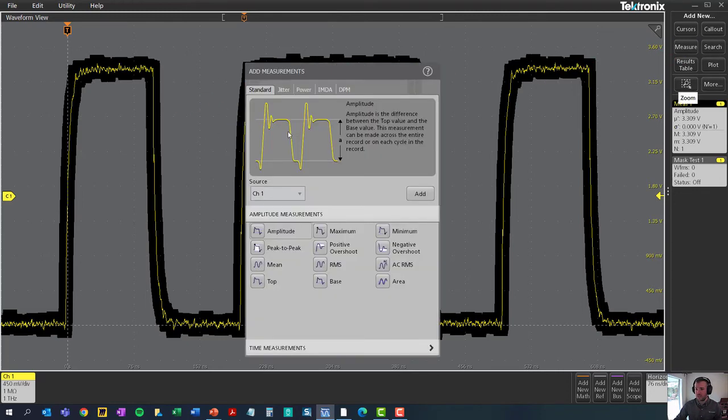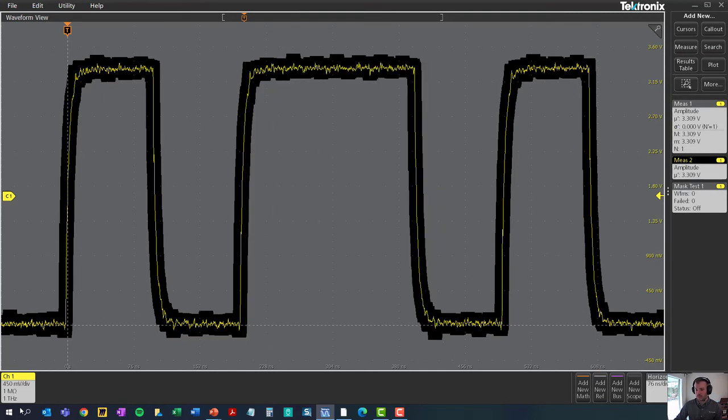Everything that we were doing, right? Drag and drop, add a measurement. I can turn channels off. I would be able to pull in references, and using this Tekscope, I can pull together dozens of signals. So you're no longer limited to 8 inputs, but many more, 16, 32, and you can do more complicated analysis. You just need to think about how you trigger those multiple instruments, and when you pull them back into Tekscope, then how to align them in time.